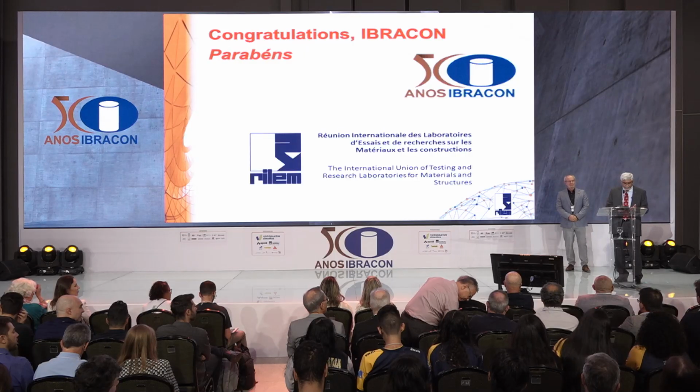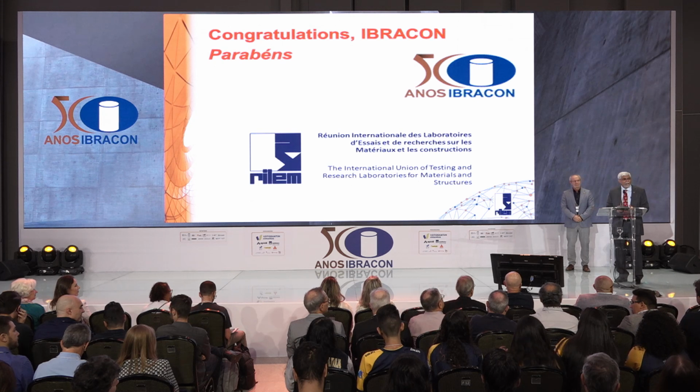Obrigado. We have experience with 3 types of materials. With slag, we have gone up to 60%. That means the clinker is about 35%. And 60% GGBS. With fly ash, we have gone up to 30%.